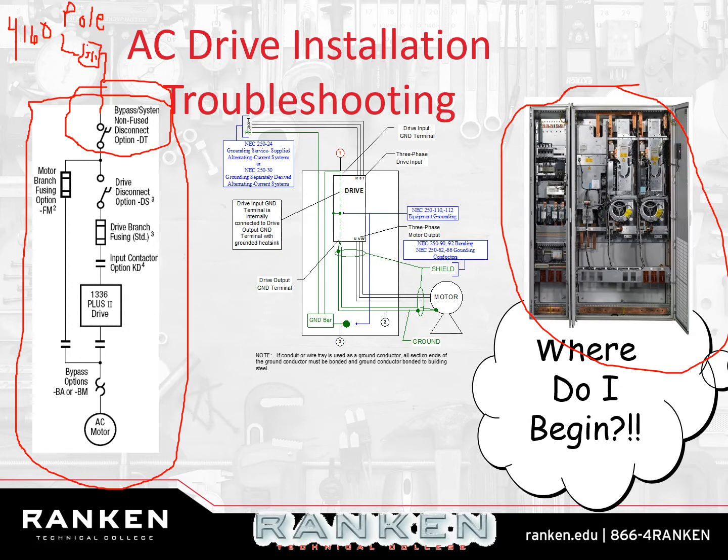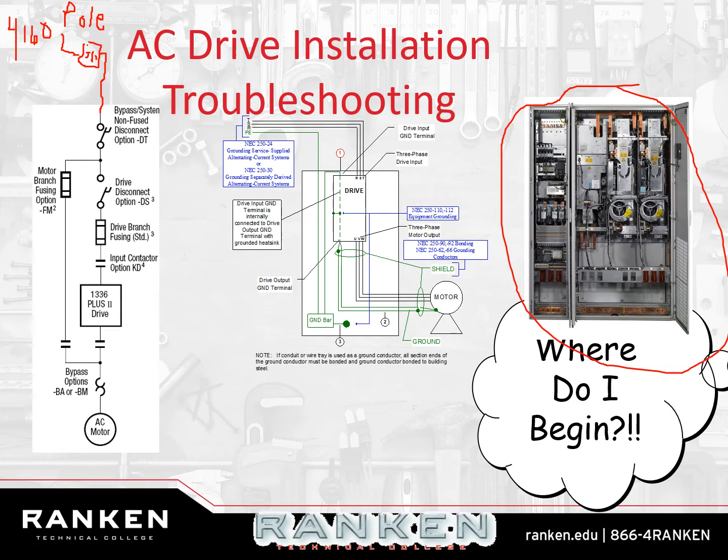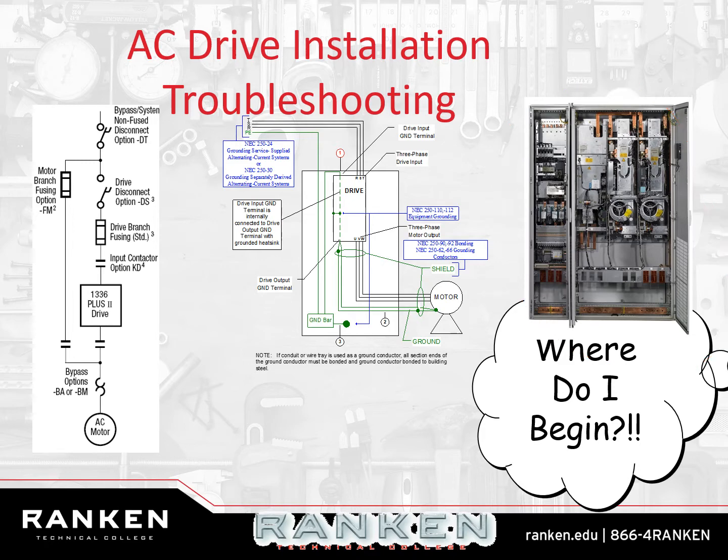If I want to shut down the entire circuit, how do I do it? Well, in our lab or in our shop, it would be the big breaker panels that are on the wall. You could go over and shut off those breaker panels and kill all the power going to all of the three-phase panels.